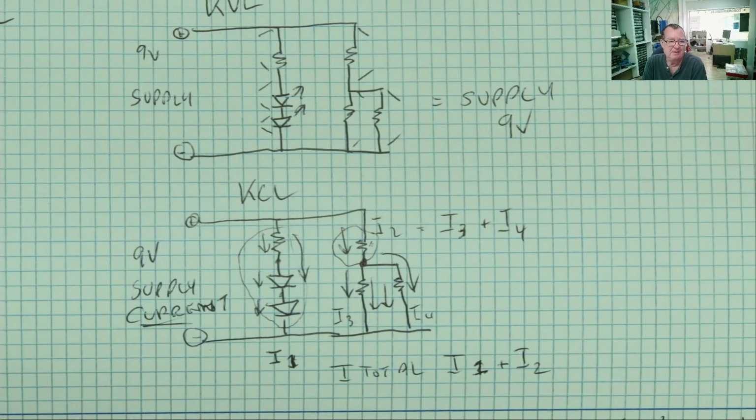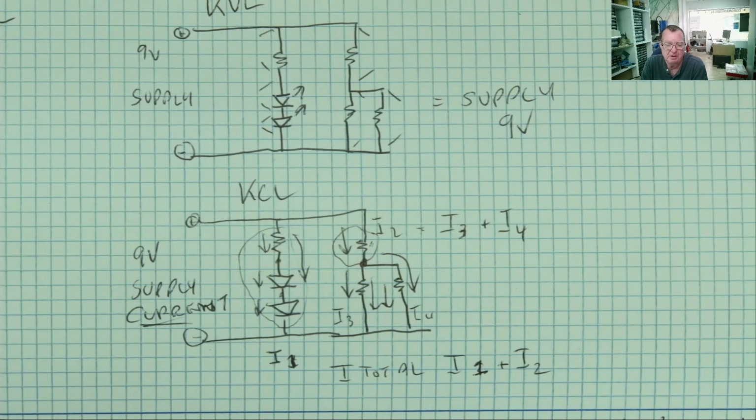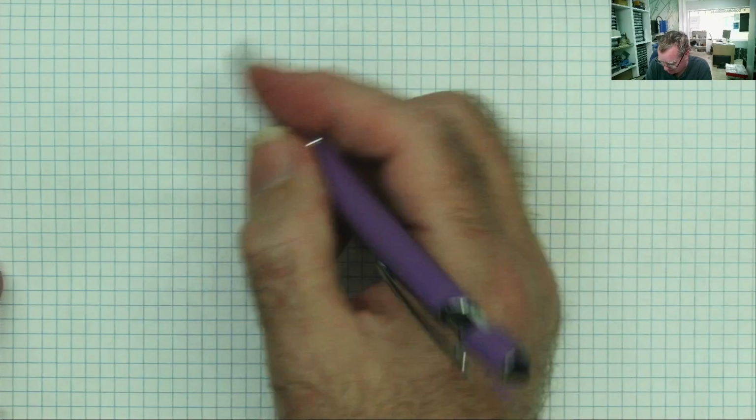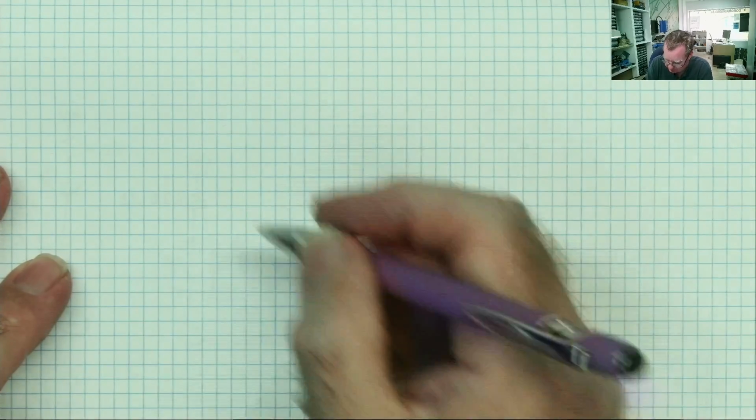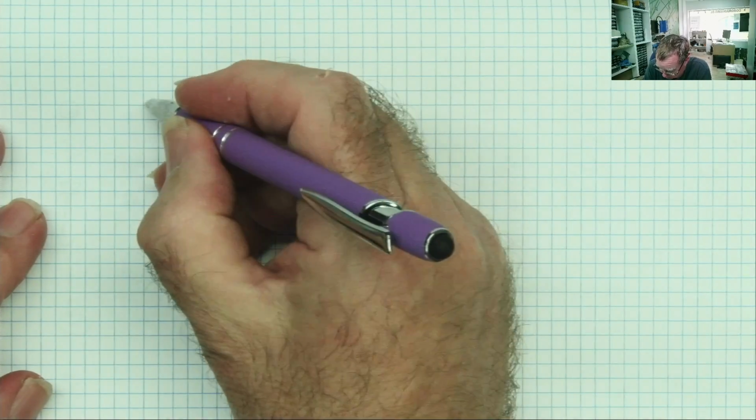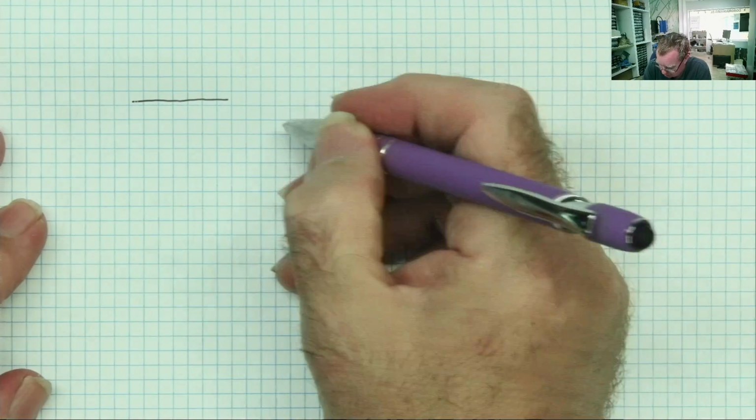You see, we have in modern electronics a lot of circuits that run from low voltages. So we normally have a higher supply voltage, 12 volts, 5 volts, 9 volts, something like that. And circuits, microcontroller or microprocessor type circuits running at 1 volt or 0.9 volts, 1.2, 1.5 and such like. And that means that devices these days contain a lot of these sort of circuits. A lot of people call this a buck converter. It's not actually. It's a synchronous converter.